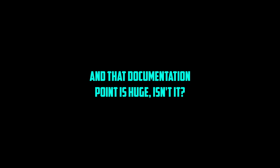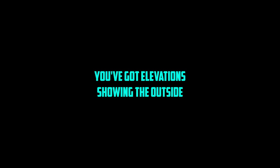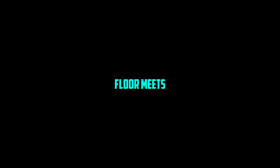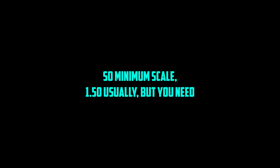And that documentation point is huge, isn't it? Construction drawings aren't just pictures. They are the absolute core language of any project. So how detailed are we talking? I know there are different kinds. Oh, incredibly detailed. You've got elevations showing the outside look, doors, windows. The handbook says minimum scale 1:100 for those. Okay, and sections. They're like cutting the building open vertically. Exactly. They show the inside, how things are constructed, floor meets wall, roof structure, that sort of thing. Needs more detail, so minimum scale 1:50 usually.